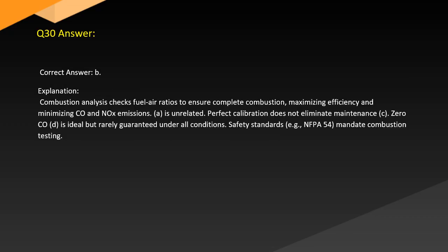Answer. Correct answer: B. Explanation: Combustion analysis checks fuel-air ratios to ensure complete combustion, maximizing efficiency and minimizing NOx emissions. A is unrelated. Perfect calibration does not eliminate maintenance. C. Zero CO, D, is ideal but rarely guaranteed under all conditions. Safety standards, e.g., NFPA 54, mandate combustion testing.